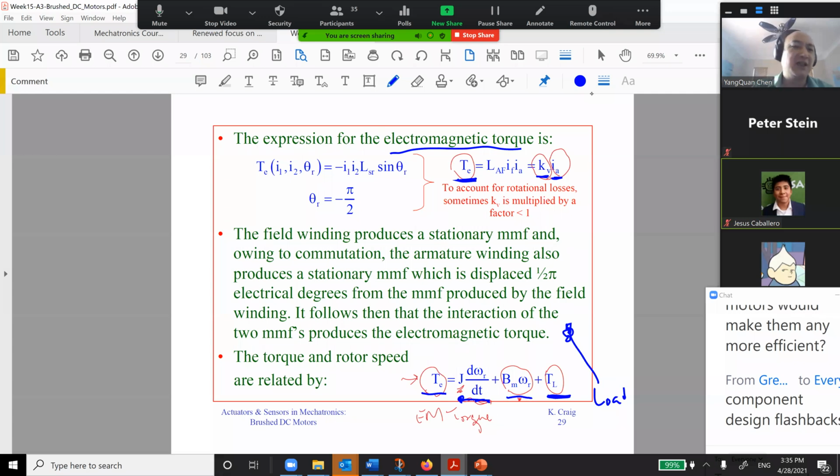And this, of course, is damping, okay? Viscous damping. That this Bm is a viscous damping coefficient proportional to my speed. The bigger the speed, the bigger the resistive, frictional torque I have. It's friction torque. So then this is the balance, okay? Or in other words, I fix this one on this side, then move everything on this side, okay?